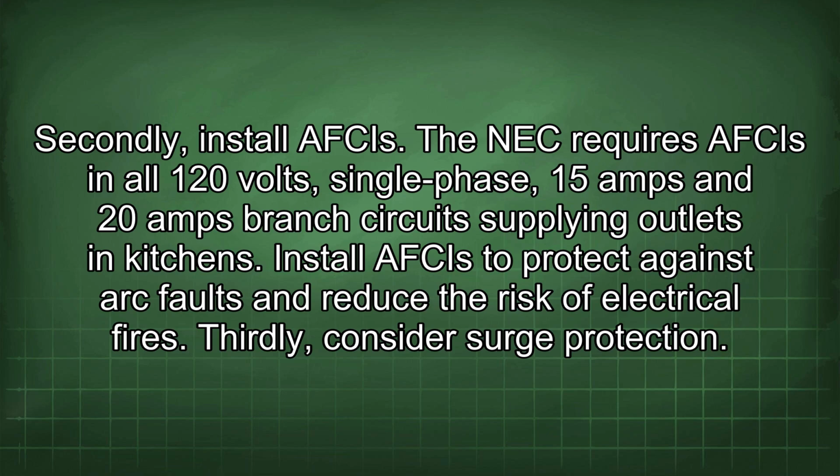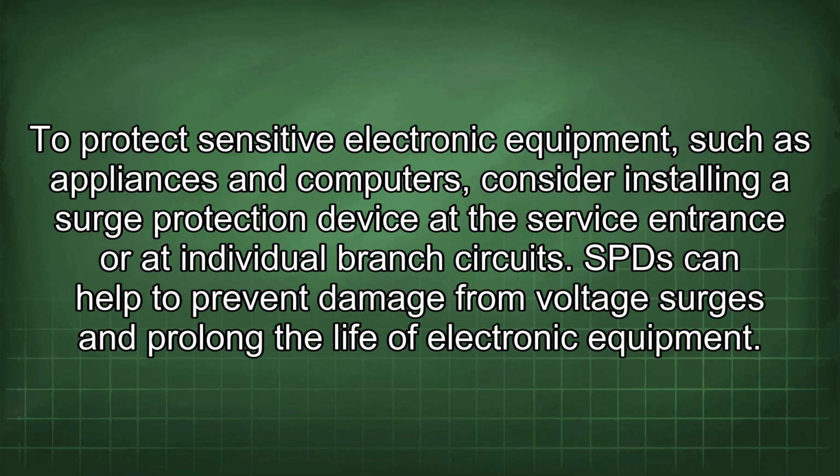Thirdly, consider surge protection. To protect sensitive electronic equipment, such as appliances and computers, consider installing a surge protection device at the service entrance or at individual branch circuits. SPD can help to prevent damage from voltage surges and prolong the life of electronic equipment.